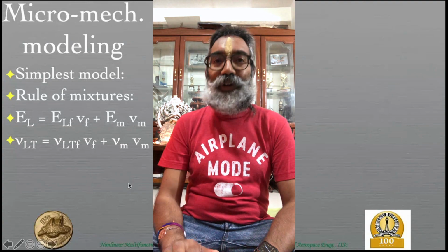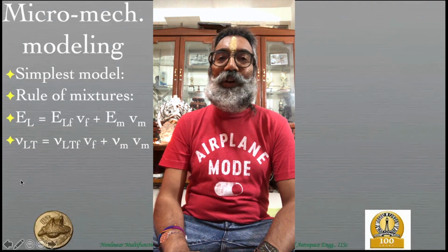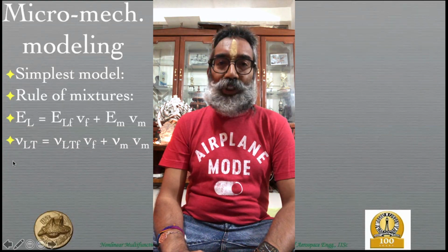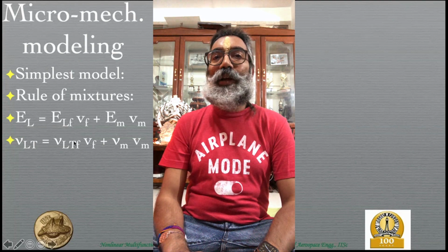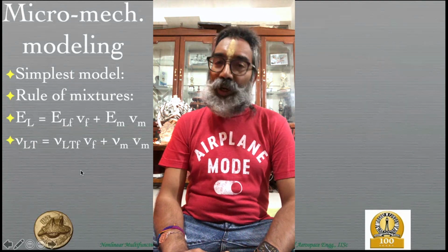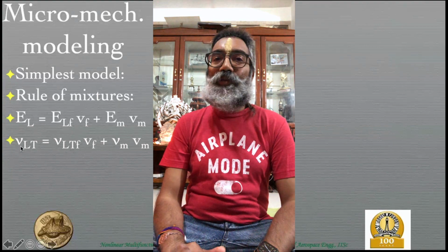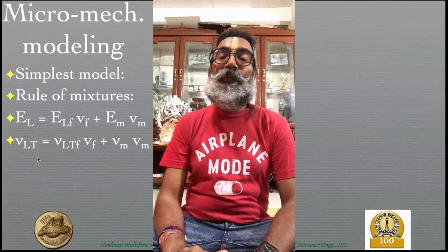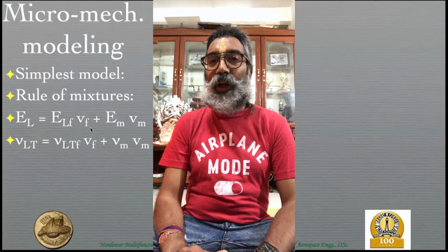On the other hand, this is something we will see a lot of, these surprises, when we go into composites. The Poisson's ratio for a composite need not have those limits. There can be some composites, depending upon, of course, the individual values of these, that can have values which are higher than 0.5 and lesser than -1 as well.